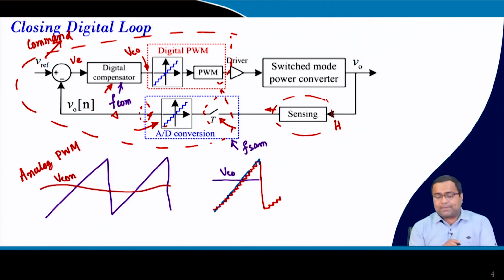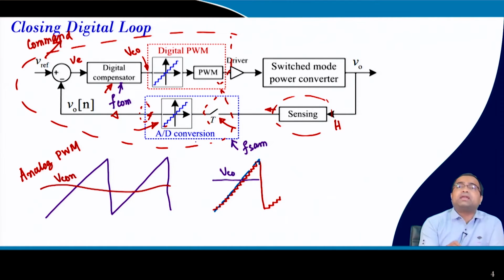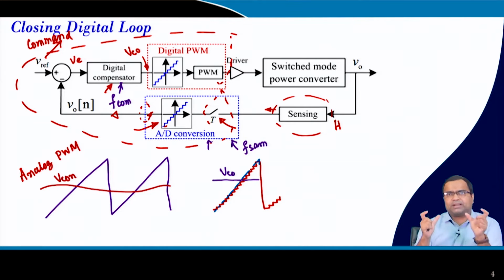But sometimes, in some cases we may sample at a higher rate, but we may compute at a lower rate, because the ADC can sometimes be used for a kind of transient detection circuit, where we need to sample at a faster rate to identify when the transient happens, or in some cases we are just looking at the error voltage, whether it goes beyond a limit or not.